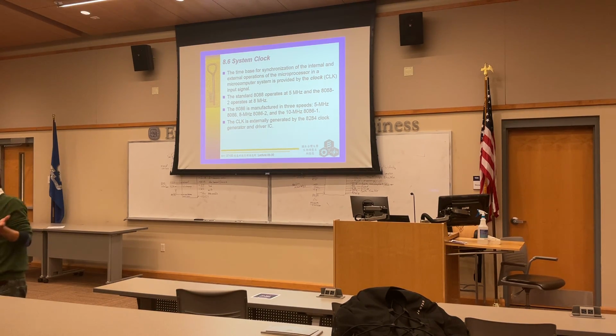Now, but our computer is digital. Quartz is analog vibration. That means what? We need a converter, a circuitry to convert a mechanical oscillator vibration clock period into the electrical signal 0101. So this is a clock generator.